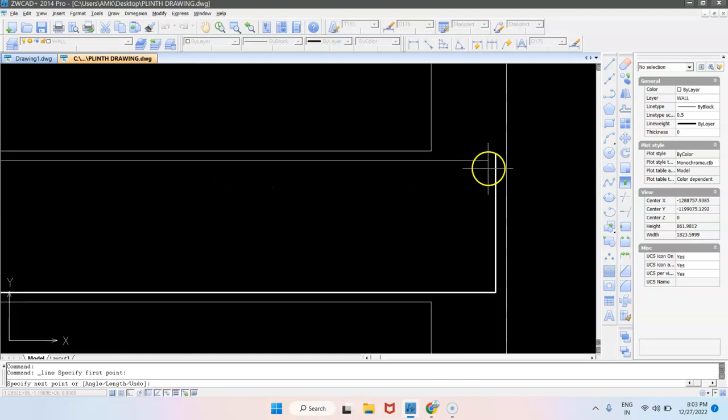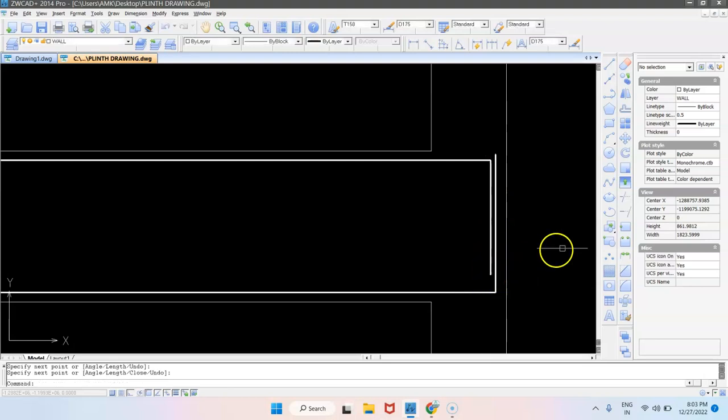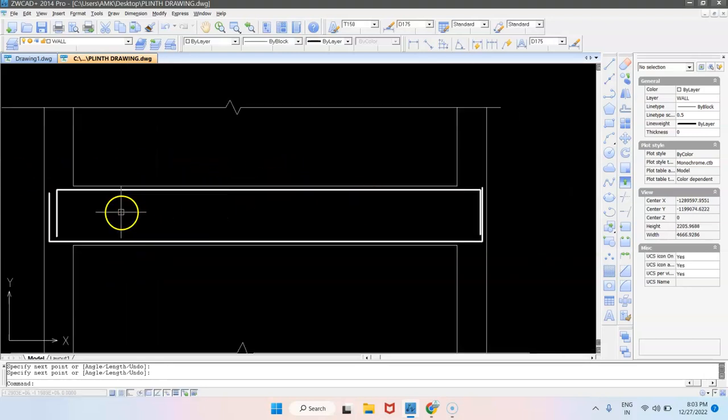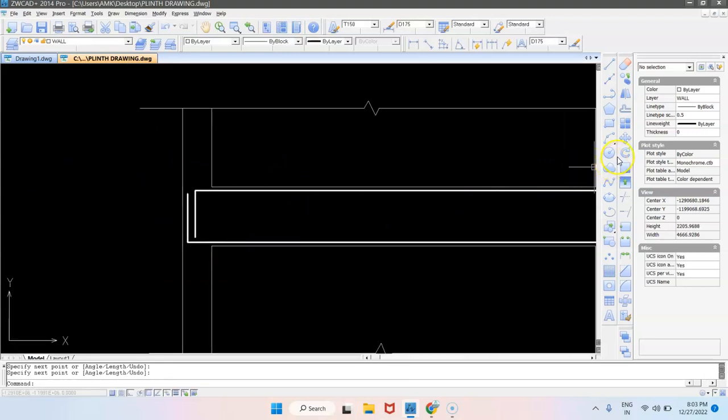This bar is also going to be bent down like this, and same way here, and that is again for purposes of getting the necessary development length. So this is important to note, that we have to draw both these bars like this, bent down to the full depth of the section.